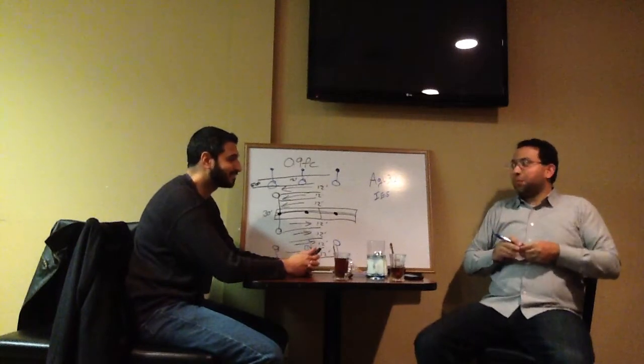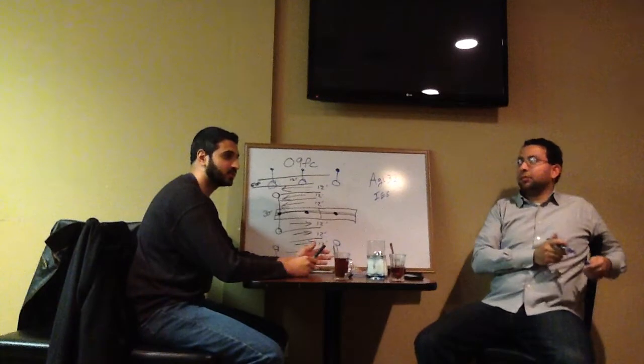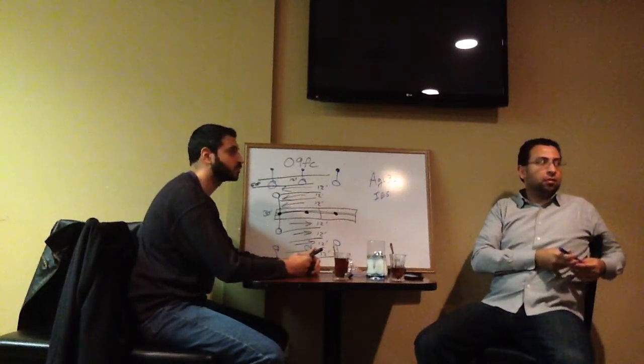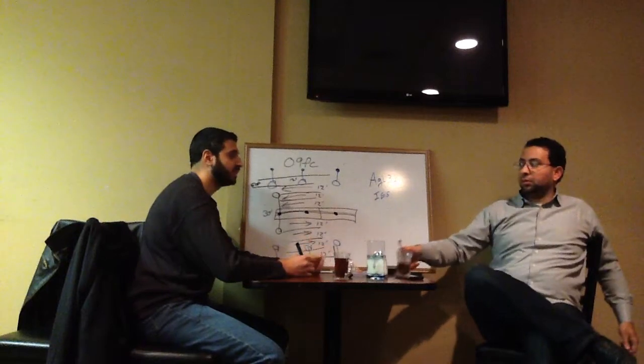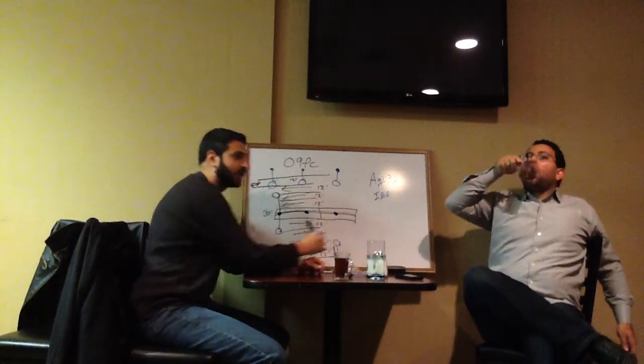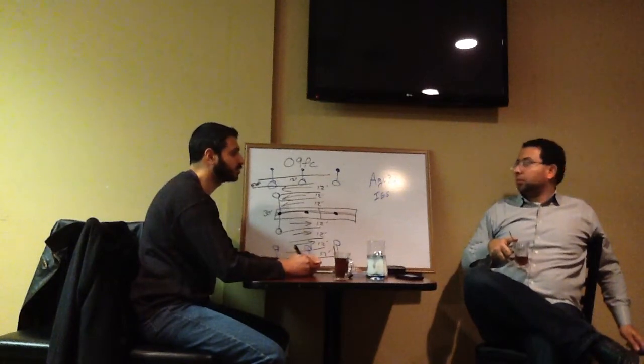Once we decide on the fixture, usually they have them uploaded to their website where you can just download an IES file if you want to test it out. So you would go to the website, look for the model of the fixture that you're using, and then usually they'll have a link to download the IES file. If they don't, you have to give them a call and ask for it.